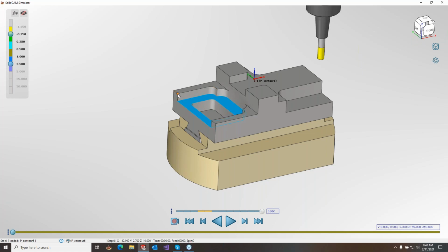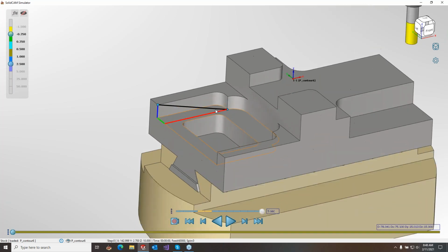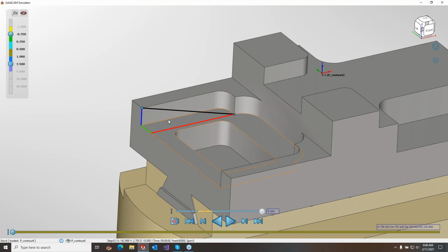You can also do measurement between items. So for instance, I can highlight 2 points, and then we get a 3D measurement. Just as we get in SolidWorks, we get the 3D distance, we get the distance in X, Y, and Z, and you can highlight multiple things this way. So we can highlight between 2 edges. We can highlight between a face and a point. So this is similar to SolidWorks, so you kind of have to experiment with all the things that you can measure, and we will continue to hopefully add more measurement things in here.